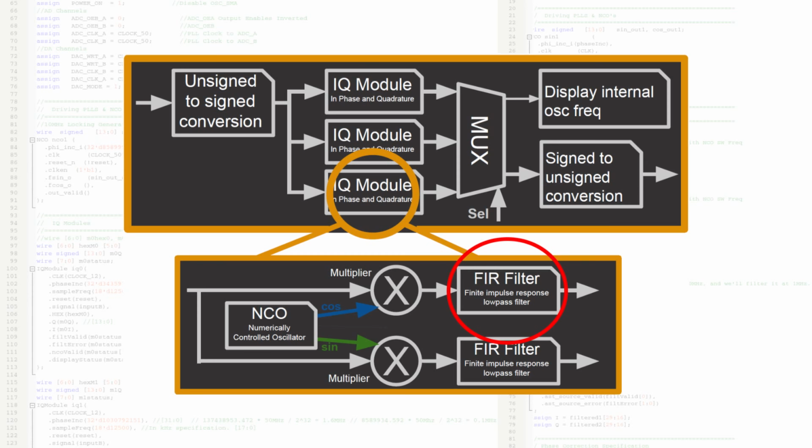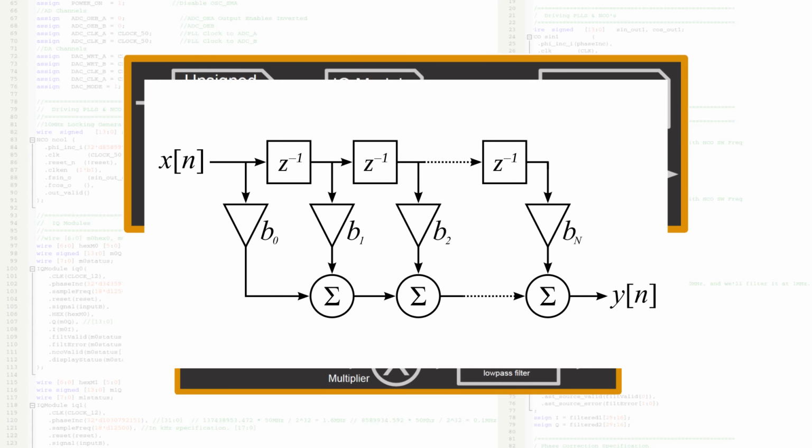And so what we implement next is an FIR filter, and this is a finite impulse response filter. How it works is it takes input samples and buffers them. Then, by using a set of stored coefficients in memory, it multiplies each of these buffered values and adds them together to give you a result. Tuning these coefficients in a certain way allows you to filter out certain frequencies of data running through your system and cancel them out while allowing other things to pass through.